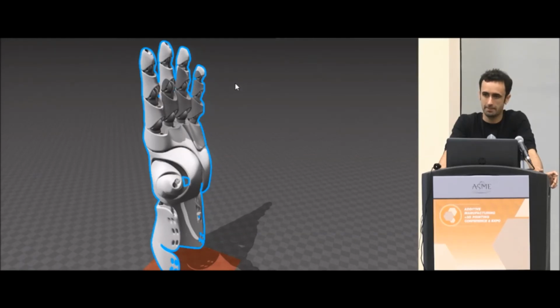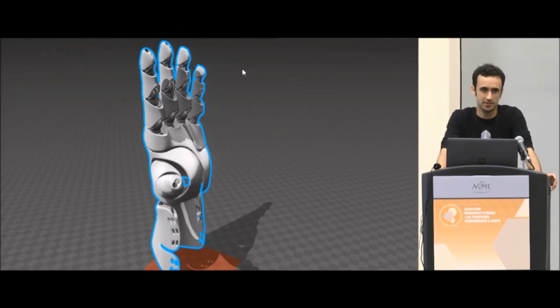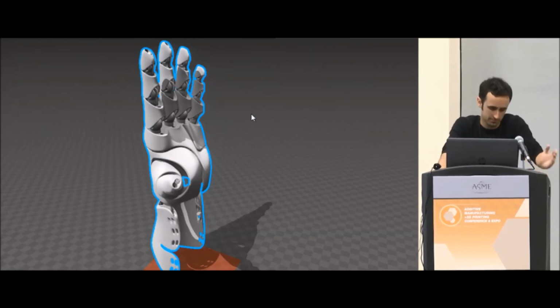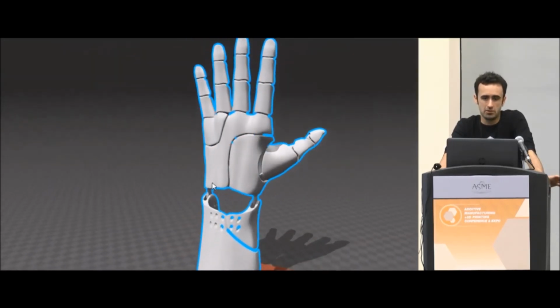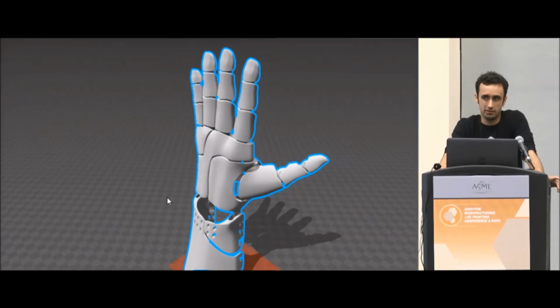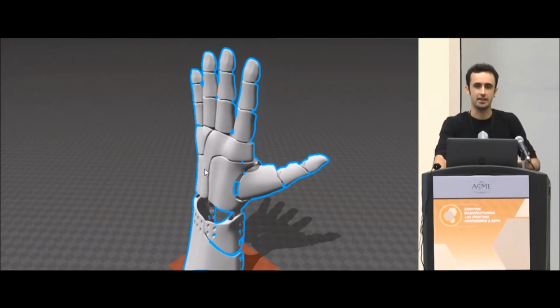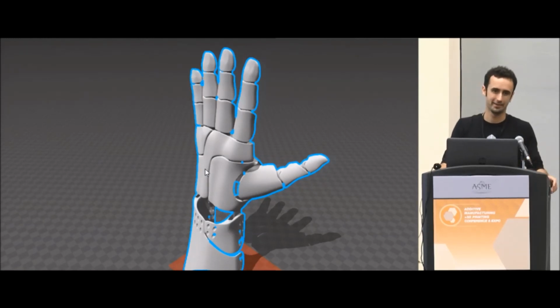tolerancing is important, but each printer is different, each material is different, everything is different. A lot of them will have that information set up, like accurate to 50 microns, on their website or on some user guide page. But the first time I print something I figured should be assembled, I'm expecting it to fail. I'm not saying I think I'm going to get it right. I would like to get it right, but I'm willing to err on the side of it might not, just based on slight differences.